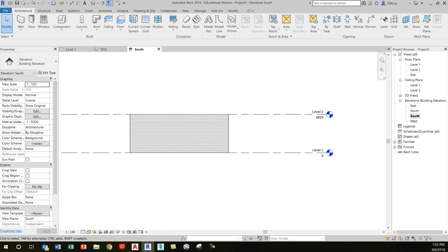And then down here in the bottom right, there's a few tools that we'll get to eventually. An important one is this little filter command. We'll come back to that later, but when we want to select something and it's just a tiny little thing that's hard to grab and it's around a whole bunch of other objects, we can select the whole batch and use the filter to just refine our selection and get just that one object that we were looking for. So we'll come back and talk about filters later, but that's where that one is.